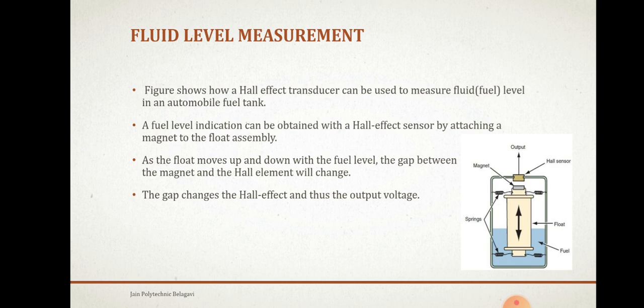You can see in the diagram, as the float moves up and down with the fuel level, the gap between the magnet and the Hall element, this Hall sensor, will be increasing or decreasing as the fuel in the tank is reduced or increased.